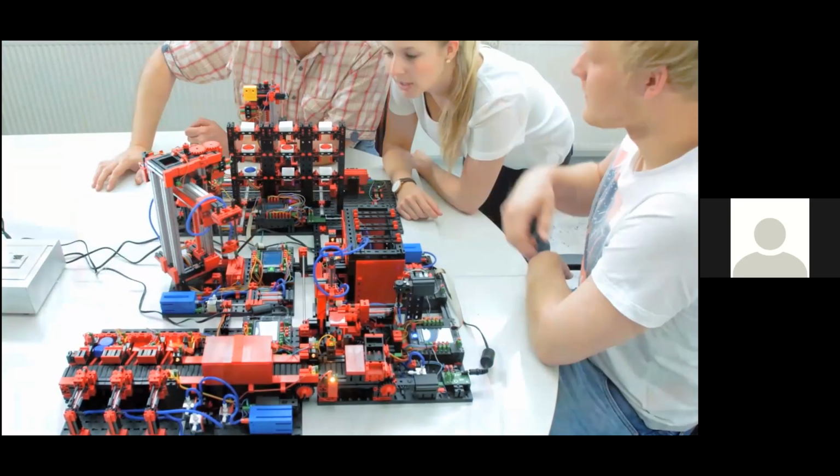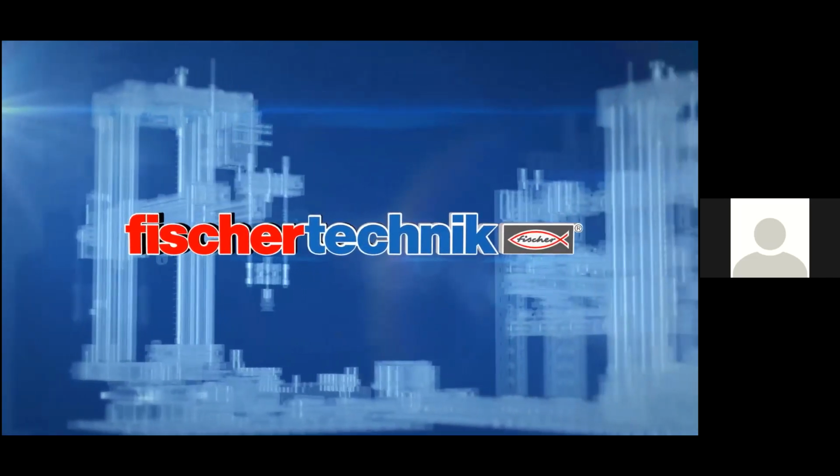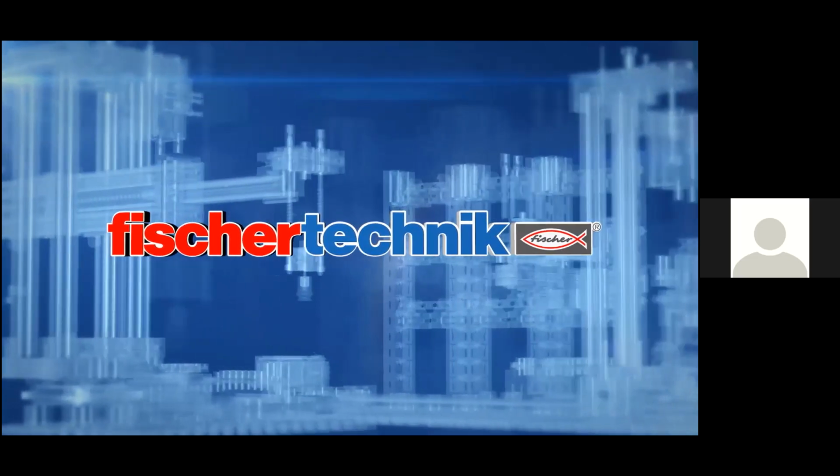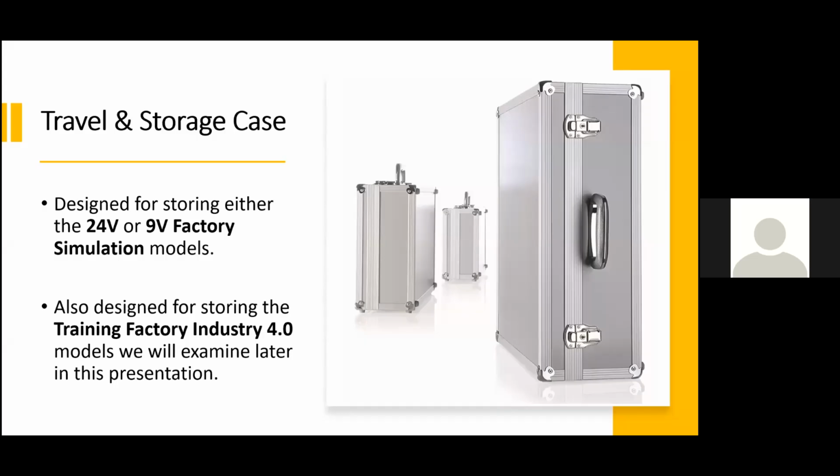Again, each station of the 24-volt version has a relay board for motor polarity reversal and both a multi-pin connector, 34 pins with a grid of 2.54 millimeters, as well as additional PCB terminals with pushing connections for all inputs and outputs.